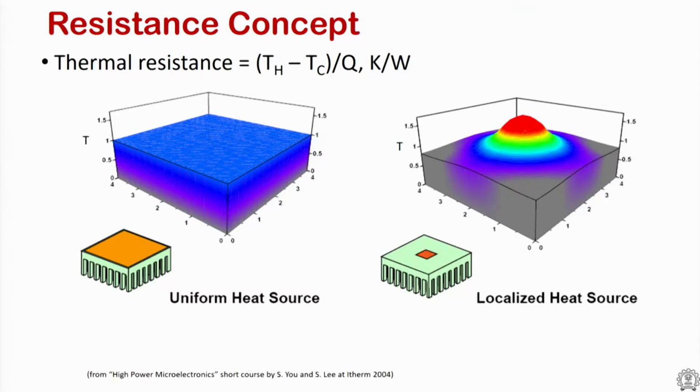When you are talking about heat dissipation by natural convection, often you find that radiation becomes an important contributor. So when looking at thermal design of smartphones and handheld devices, you often rely both on radiation as well as on natural convection cooling. So we'll look into some design or more interesting concepts.